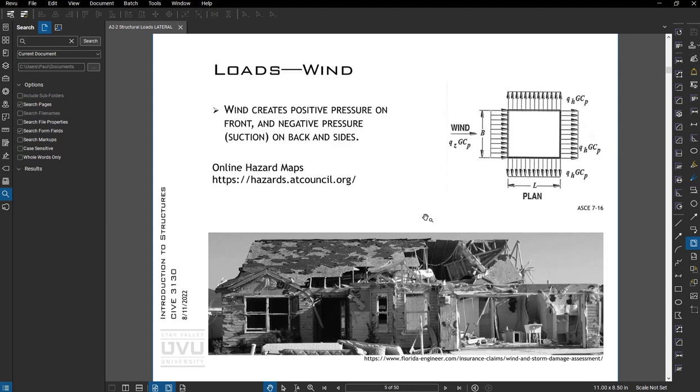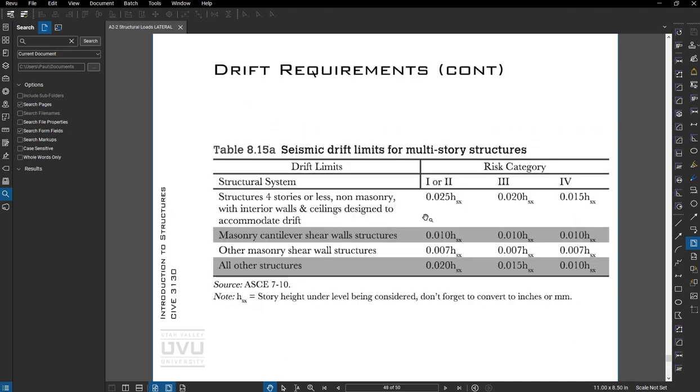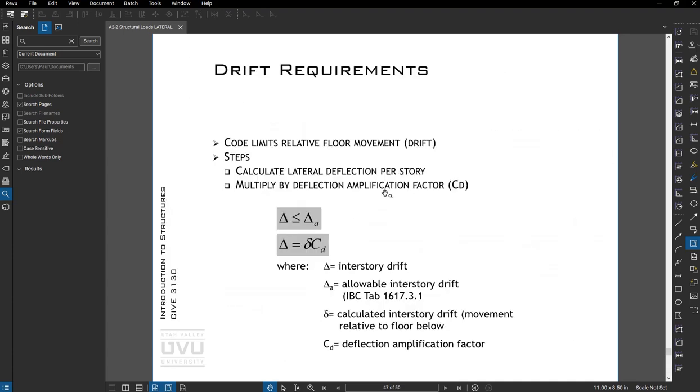the energy. But I want to make it perfectly clear that we can design to the current seismic codes, have a major earthquake happen, and our building will be substantially damaged. The building code does not keep buildings after a seismic event in perfectly usable condition. It's a life safety code, which means if the building didn't fall down after an earthquake, the engineer did their job.